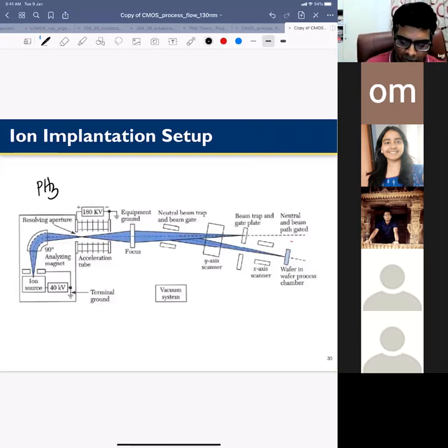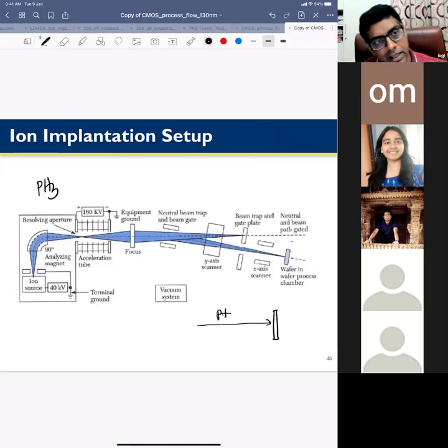So you have a wafer here, right? Your phosphorus ions are accelerated and implanted, right? But you need ions because ions can be accelerated. If you have a neutral molecule, that cannot be accelerated, right? So you implant ions. The implantation, how deep you want your phosphorus to go into the wafer, or how much phosphorus, that is your doping concentration, right? So this is defined by the dose.